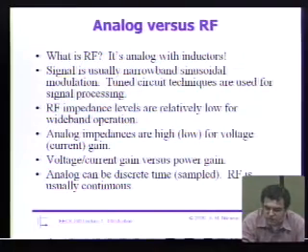Now, analog circuits, on the other hand, like high impedances for voltages or very low impedances for currents. That's because a lot of the signal processing we're going to be concerned with is on chip, and oftentimes we're just trying to build circuits to get as much gain as possible, right? If you're talking about voltage gain and you have a transconductor, obviously you want to use the highest output impedance possible.